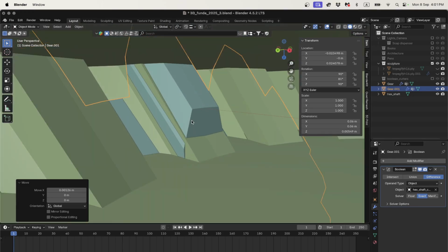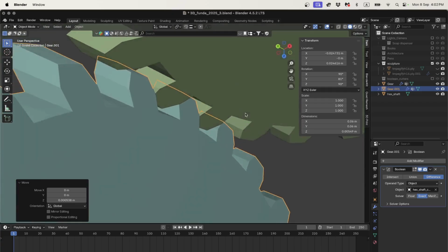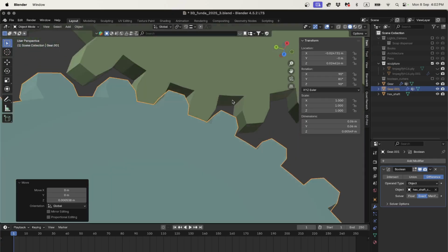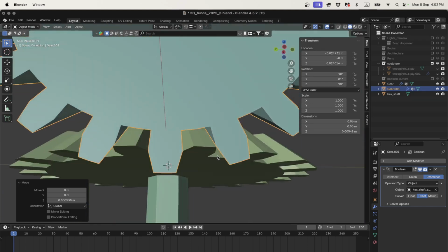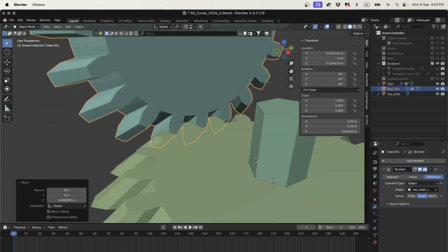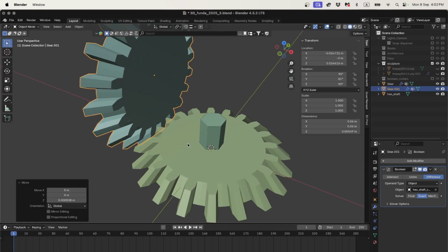And if I look inside, we'll see it. So I'm just going to GX, GZ until we're not cutting in at all. And I think that's a pretty good guess, should be within a fraction of a millimeter or so, of where our gears are definitely going to mesh. If we connect them this way, when this one turns, it will turn this one.